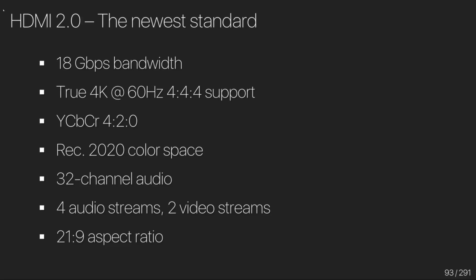Quickly. Is 4K 60 420 possible with HDMI 1.4 or not? Yes, it is. When HDMI 1.4 came out, they picked out this upcoming feature from HDMI 2.0 and implemented it early. In terms of the standard, it was defined in HDMI 2.0, but in terms of practice, it started being used before HDMI 2.0 devices were on the market. So HDMI 1.4 devices and also HDBaseT can handle the 4K 60 420 signal.